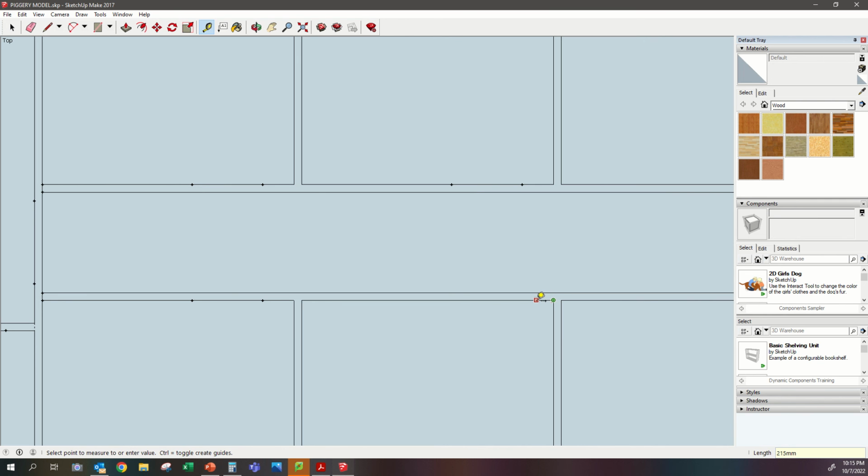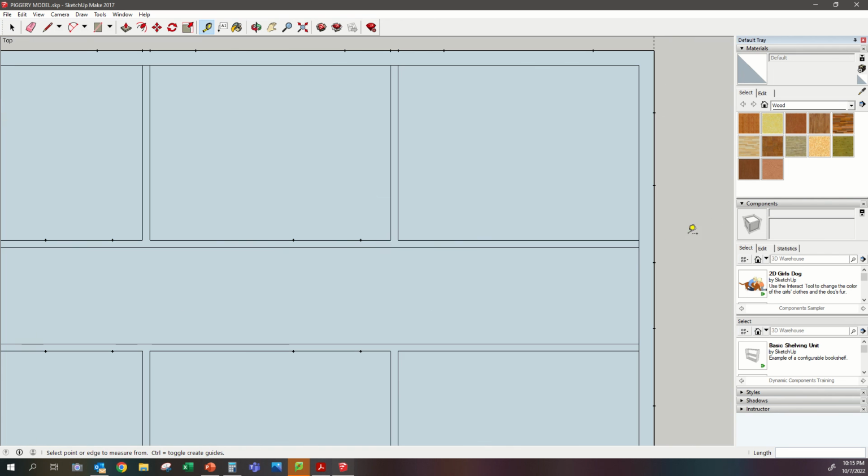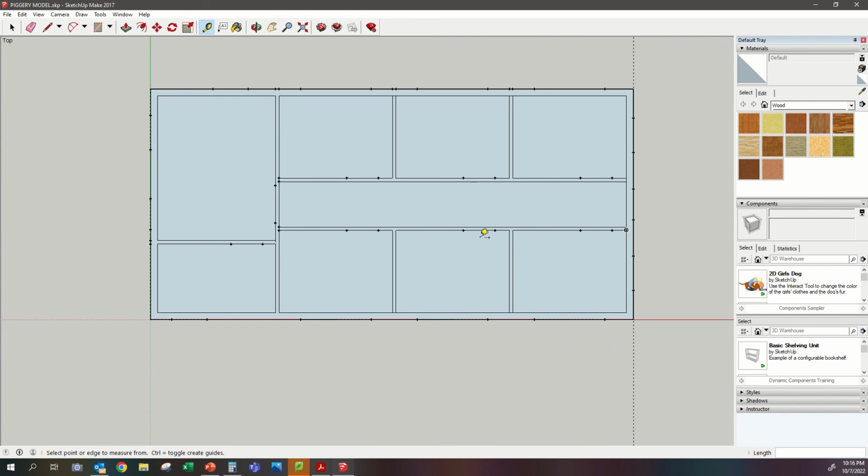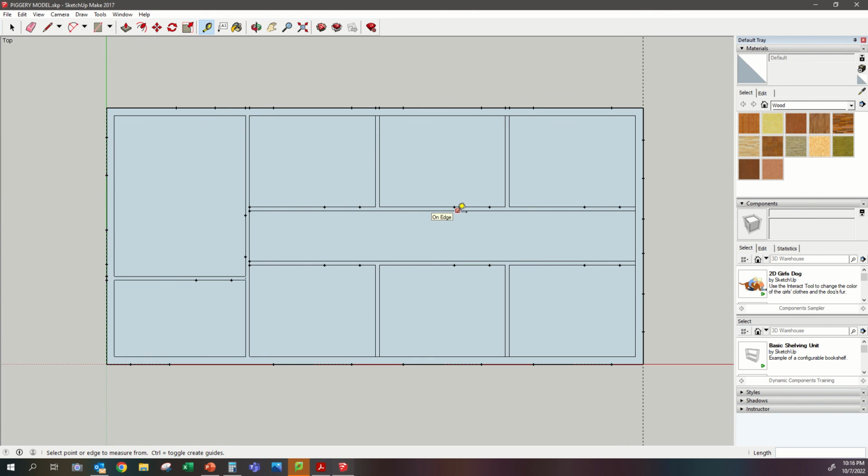Do it again, 400, enter, 900, enter. Do it one last time from the inside corner here. We're going to go 400, enter, and we're going to go 900, enter. And over here, we're going to go 400, 900. Alright, now I've gathered all the positioning, and all the relevant windows and doors that we need are all in place. So that is part 2, getting guides for all the windows and all the doors and all the openings that we need. So in the next video, we're going to start to push and pull this and create volume to this and give it some 3D qualities.